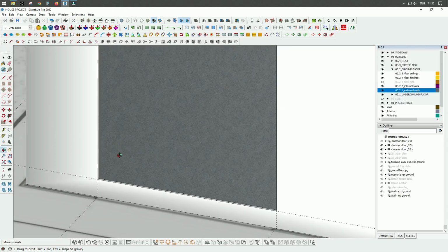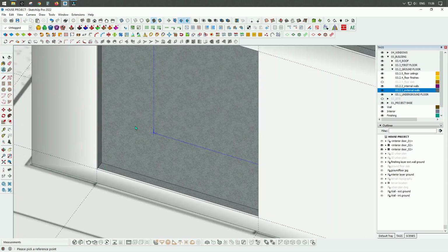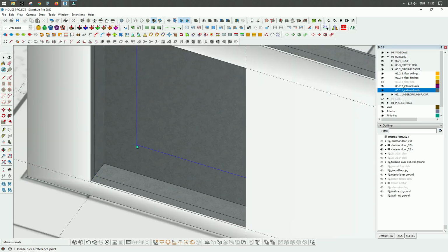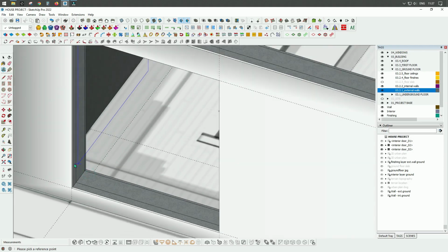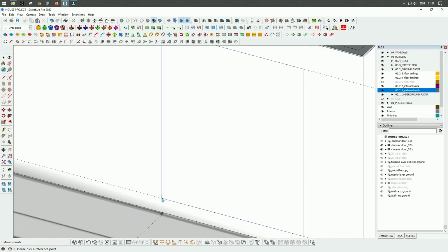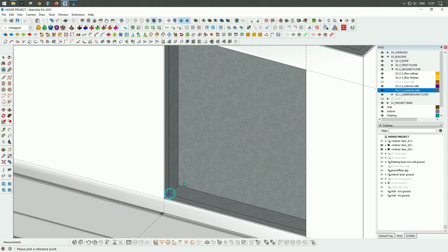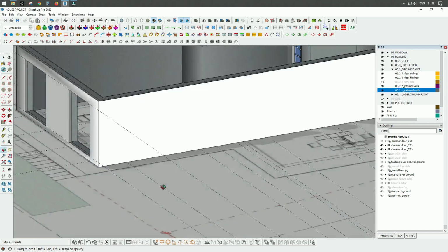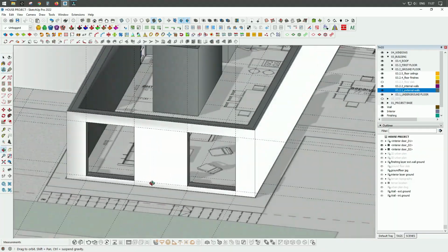Double click for the first layer of the wall, again double click for the second layer of our wall, and double click for the wall structural layer, and the final one. Now I have a clear opening for the first window, and then I'm going to create the next window, and now we have these two window openings, and we can place our windows here.